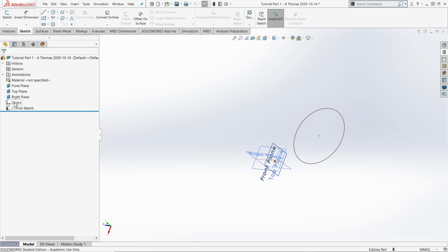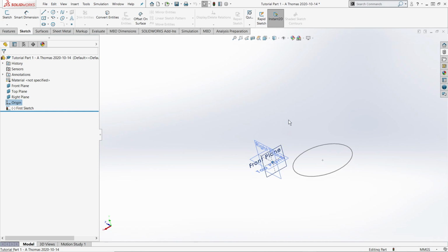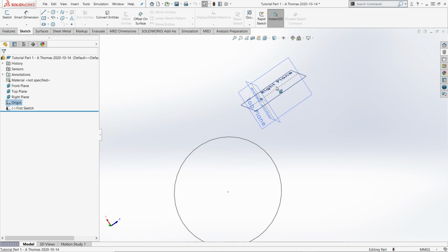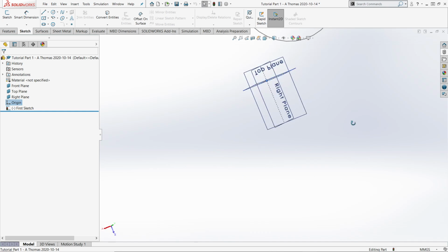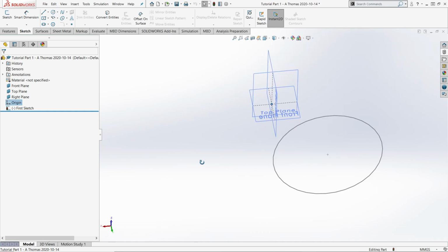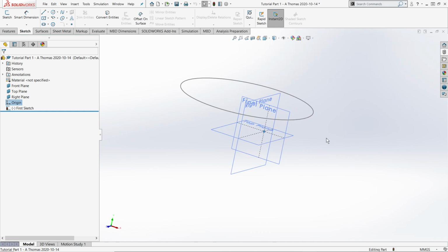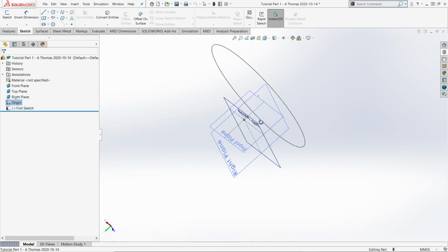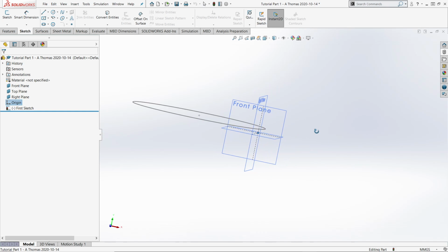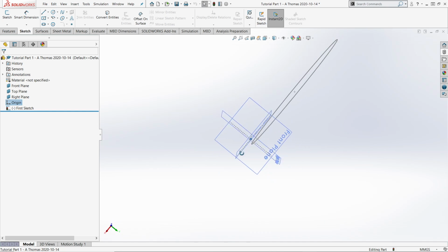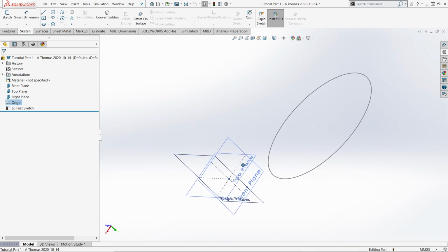I'm pretty sure this rotation, it happens, yeah, I haven't used SolidWorks in a while, so I don't actually know what it's rotating about. It doesn't look like it, yeah, it's not doing the origin. Anyway, so middle mouse button, click and hold, and drag is to orbit. If you want to pan around in your part, you're going to hold Control and then middle mouse button drag. So you can move things around. You can orbit. So nice and simple.